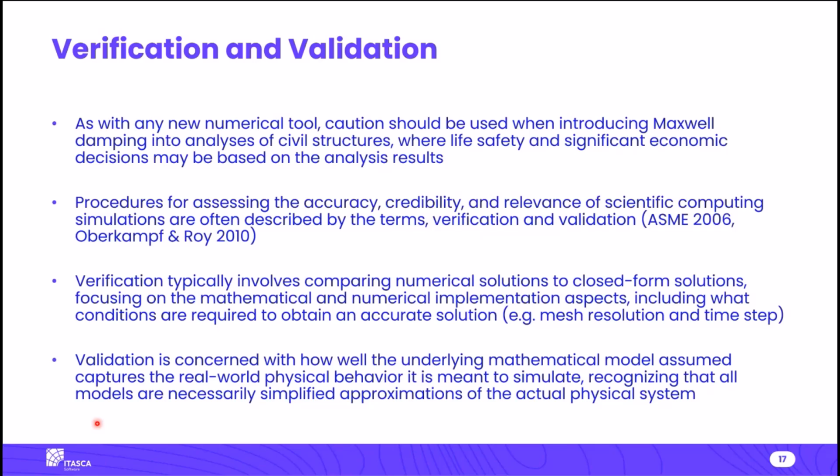Verification typically involves comparing your numerical solutions to closed form solutions. Validation is a little more nebulous, and it's concerned with: okay, you did your numerical implementation right, but does this theory or mechanism you're using really capture the real physical world behavior you're trying to simulate? To me, validation is something that occurs over experience with many projects, and then looking at benchmarking case histories. But the verification part is a little more straightforward.